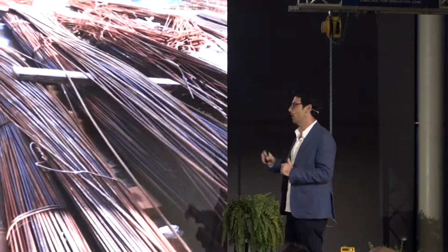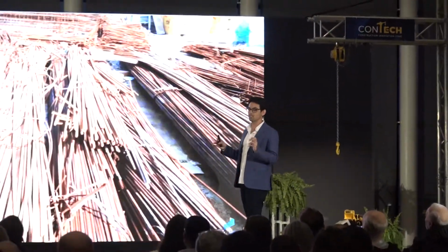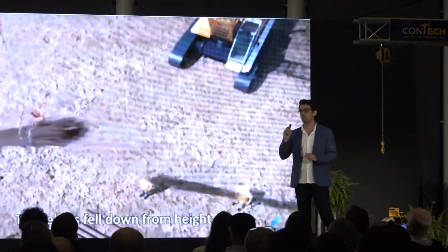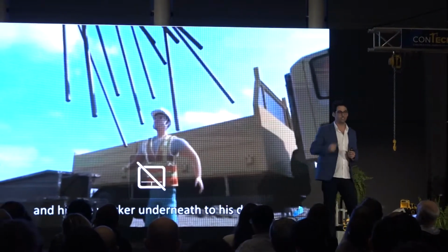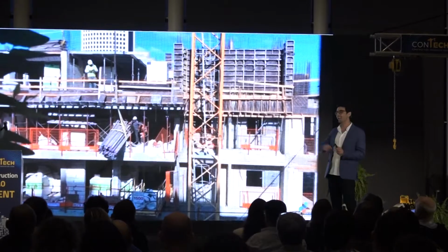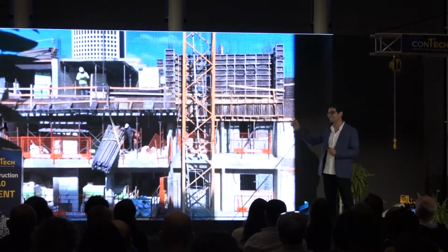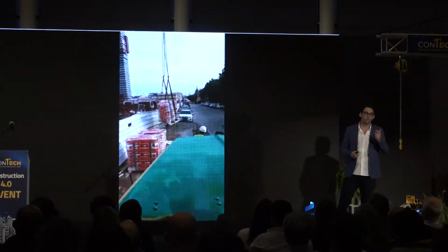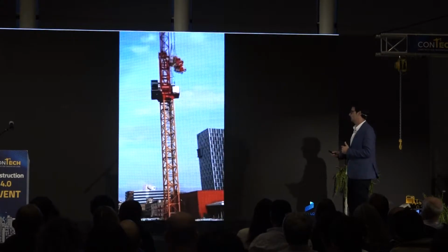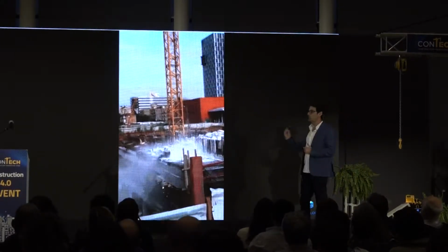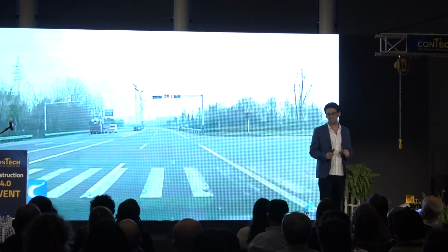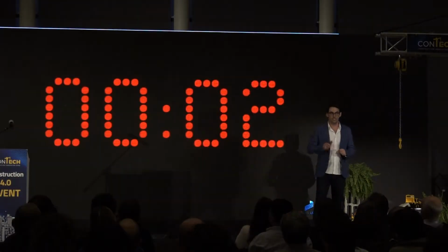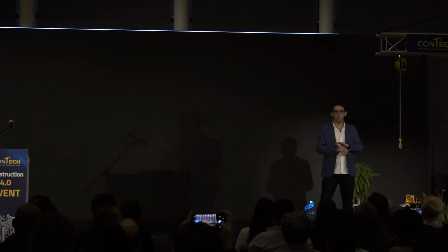But before we go there, allow me to take you through a little tour on how materials and equipment is handled today. The materials are lifted in improvised ties. Because of that, you have falling materials, which is the second highest reason for fatal safety accidents. Also, while entering and extracting materials from the working floors, sometimes you have falling workers along with them. The usage of the old, non-efficient wooden rafts that are used today cause safety accidents like we can see here. And the transportation process, not taking into consideration the sliding effect or the overturning of the cargo, ends up in tragedies. It's a ticking time bomb, and we need to put a stop to it.